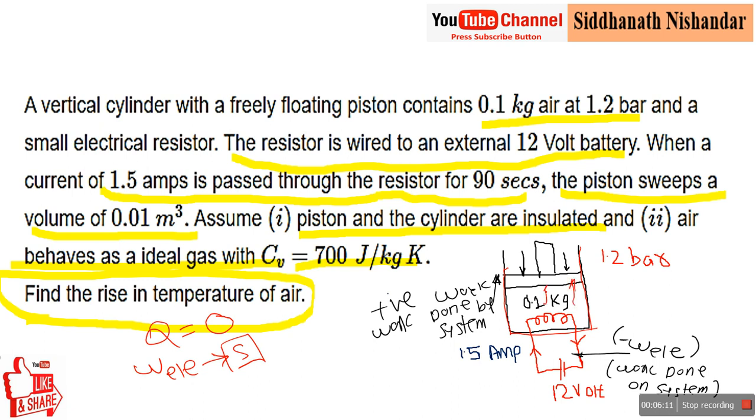Okay, when we supply the electric work here, when the gas expands, the piston moves upward, so we can get mechanical work from the system. Now we get the mechanical work. So it is very important, but we need the net change. We supply electric work and we get mechanical work. So there is a transformation of energies across the boundary of the system.